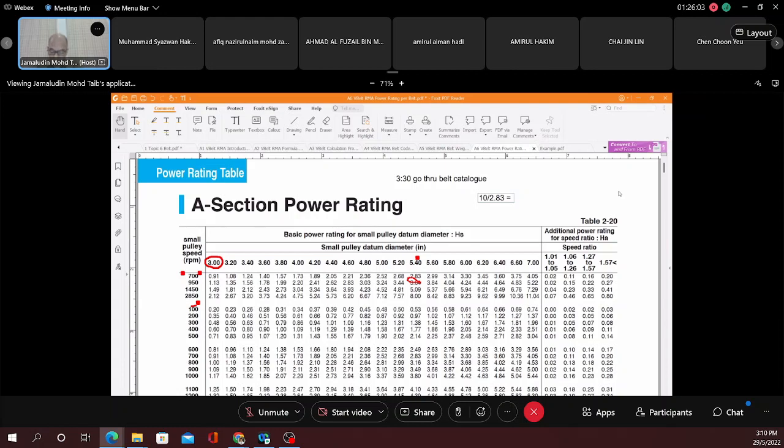10 divided by 2.83 is going to be 3.53. Then you don't just round it off. You go to the next round number. If you round off 3.1 you'd go to 3, but you need to have 4. That means the next larger whole number. That will be the belt number. That's the idea of how many belts you have. That will be the idea of step number 6.